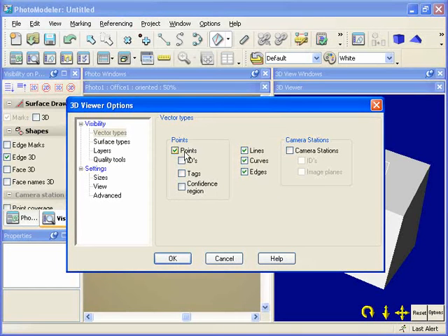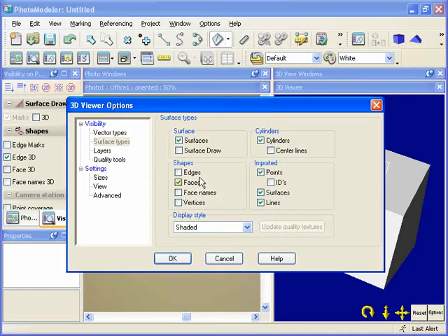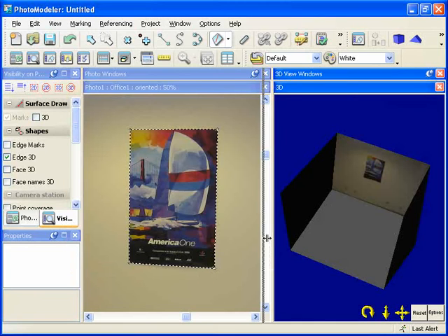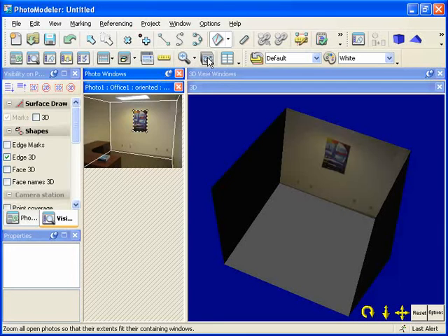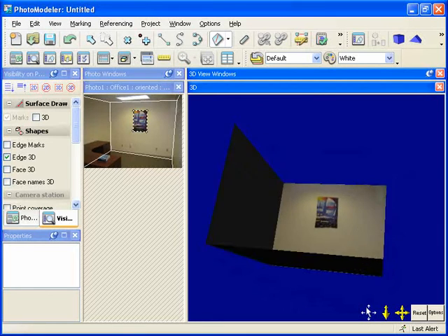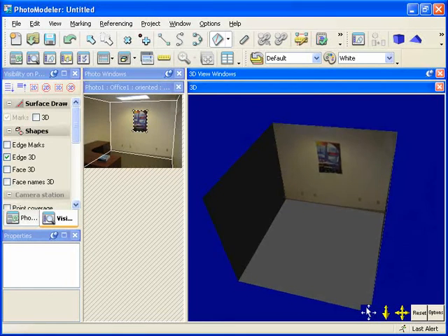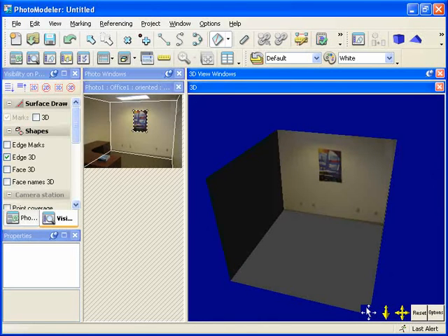We look at the textures with Fast Textures. You can see that only one face is textured. With Fast Textures, only faces and surfaces that completely appear on the photo will be textured. We use Quality Textures to improve that.